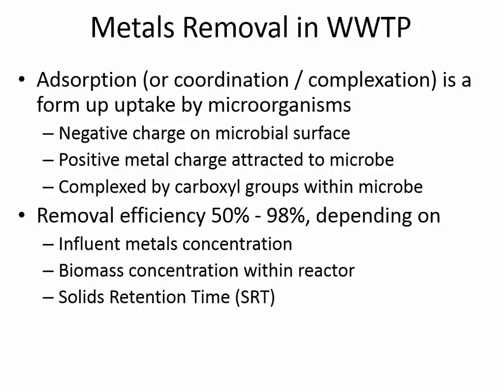The removal efficiencies vary a lot depending on the concentration of biomass in the reactor and the solids retention time and so on.